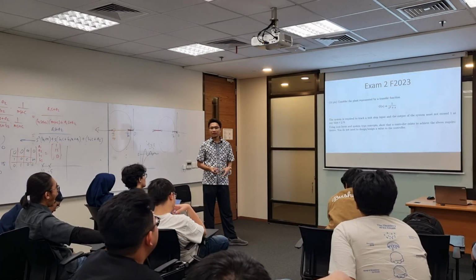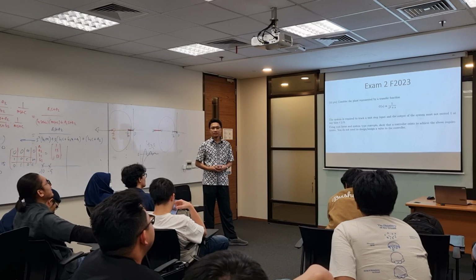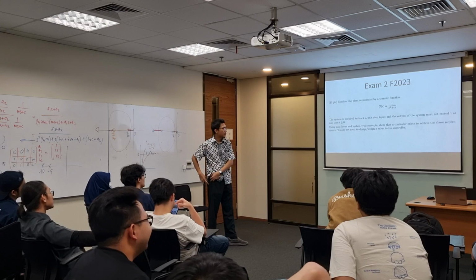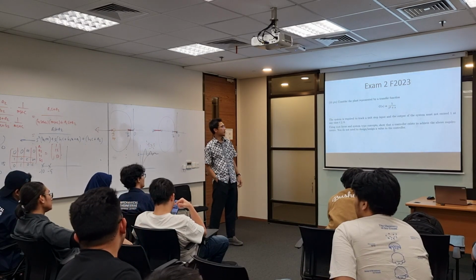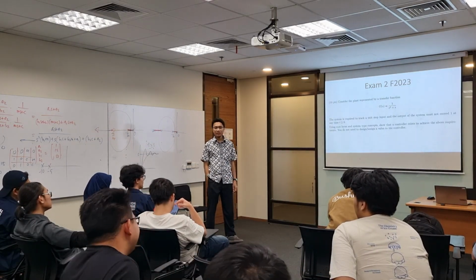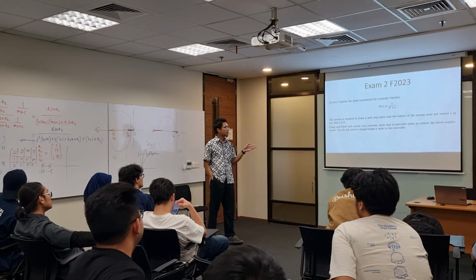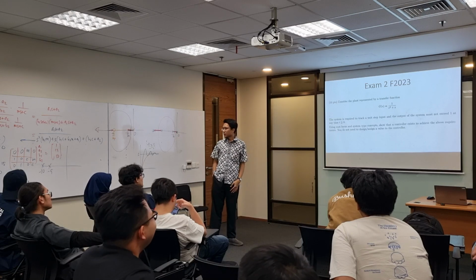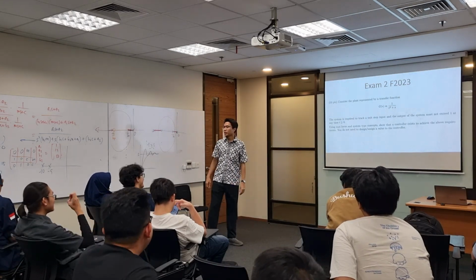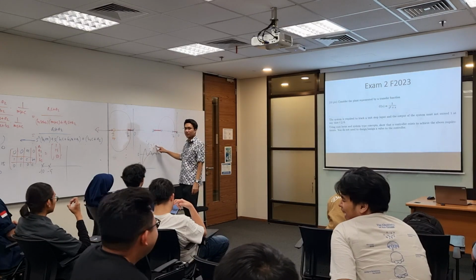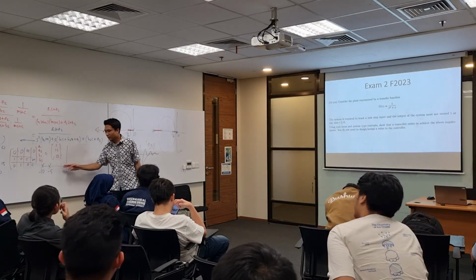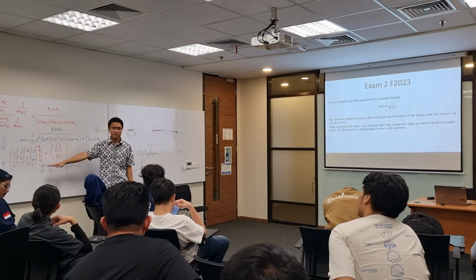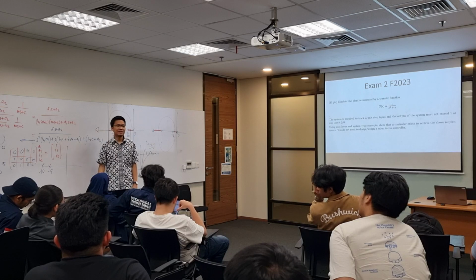What else can we find out from the problem? We haven't discussed the system type yet, so you can only answer the damping ratio. Because you know the damping ratio, where will you have your closed loop poles? Is it here or on the real axis? It will be on the real axis, that's correct.